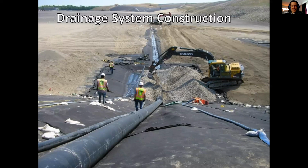And as a matter of engineering principle, it is very difficult to keep water out of places that we don't want it to go. It is far easier to collect water and give it a place to go that is constructive, and leachate collection systems effectively carry out that principle in practice. And so I would say that when it comes to controlling the risk of environmental contamination, leachate collection systems are perhaps one of the most important tools that we have at our disposal to control contamination, because we are providing a direct path for water to leave the system that doesn't involve going into the environment directly.